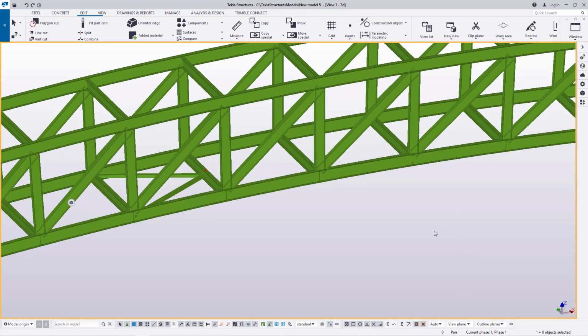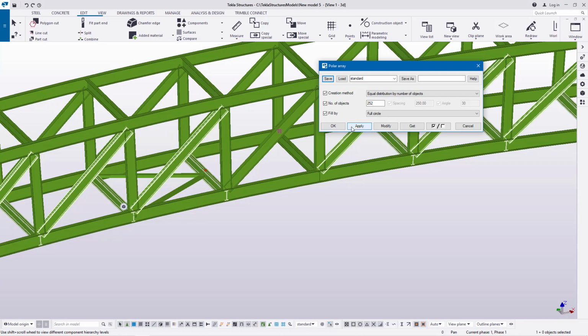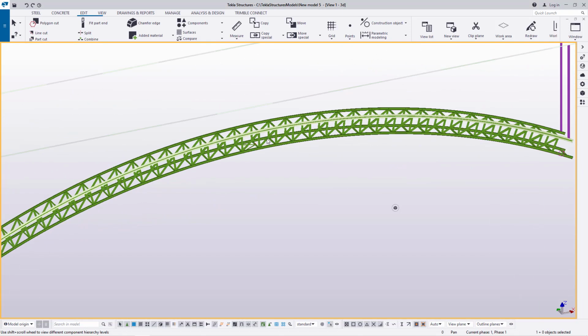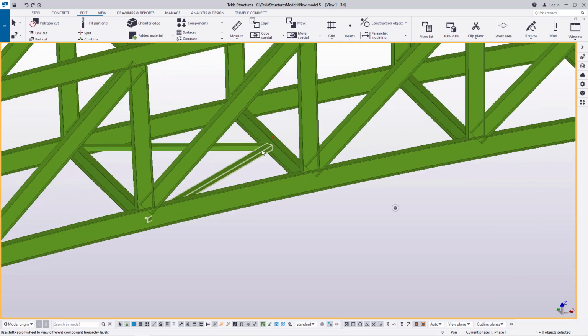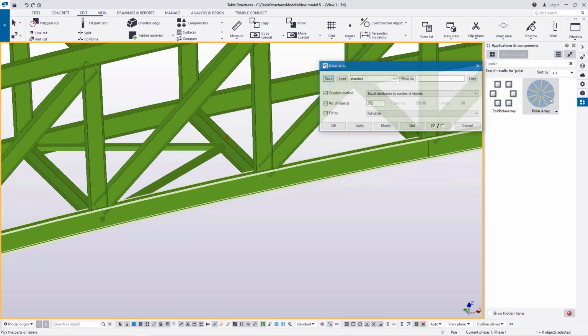It's not responding. What has just happened is because I've not enabled the assembly button here. Now I'll double click on it. I'm going to default on this number of objects here. I'll just go ahead and click apply and accept that. If I click apply and accept that, I'll be able to default on those number of objects when I use the polar array command. Now I'll come back here and invoke this polar array.